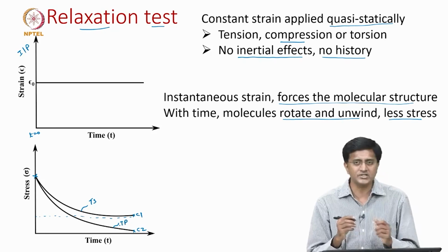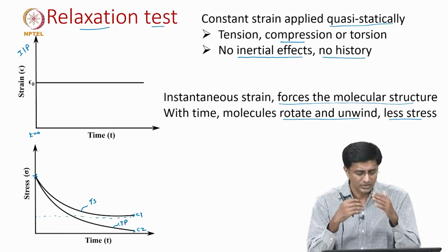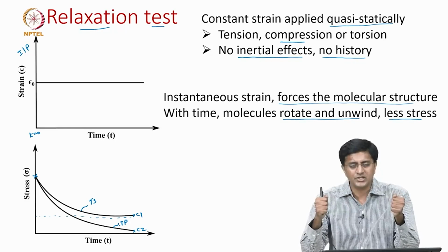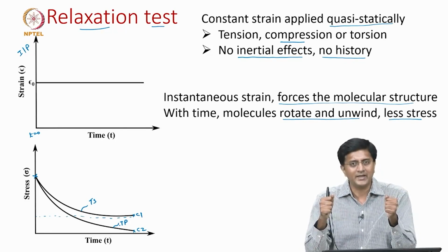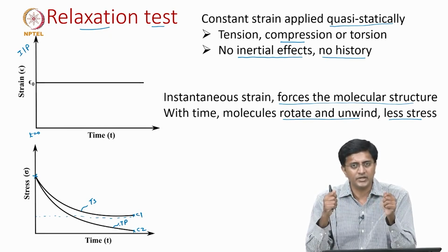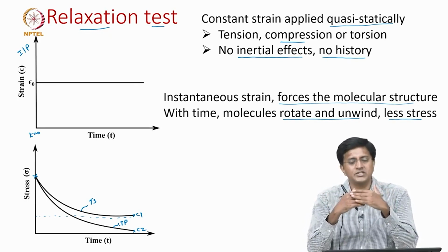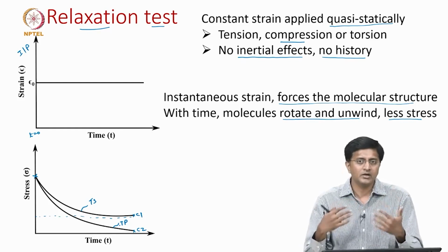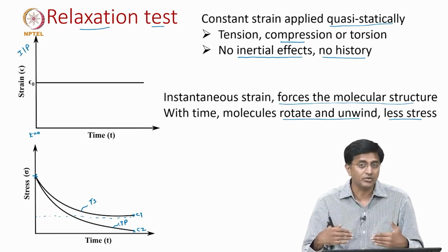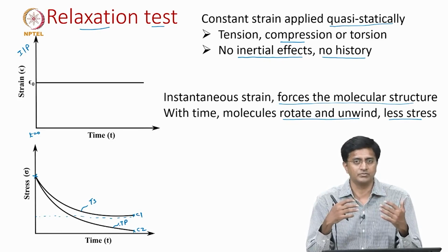So in thermoplastics, as we know, these molecular chains are bonded by secondary bonds. So once we stretch it, there is a stretch happening in the molecular chains between entanglements, but given enough time, these molecular chains can slide past each other and then reduce the stresses. If we give enough time, it flows.